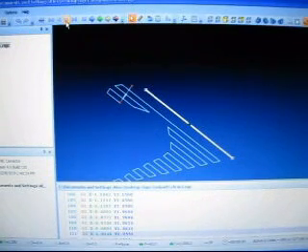Yeah, we don't want any rapid motions. That motion used to be like a rapid motion, but it was on my clearance. So as long as it's on your clearance, it's okay to rapid it through the air. But this is on the floor of the part, so I have a G1 command in there for my feed rate. If it was G0, it would be a rapid motion, okay?